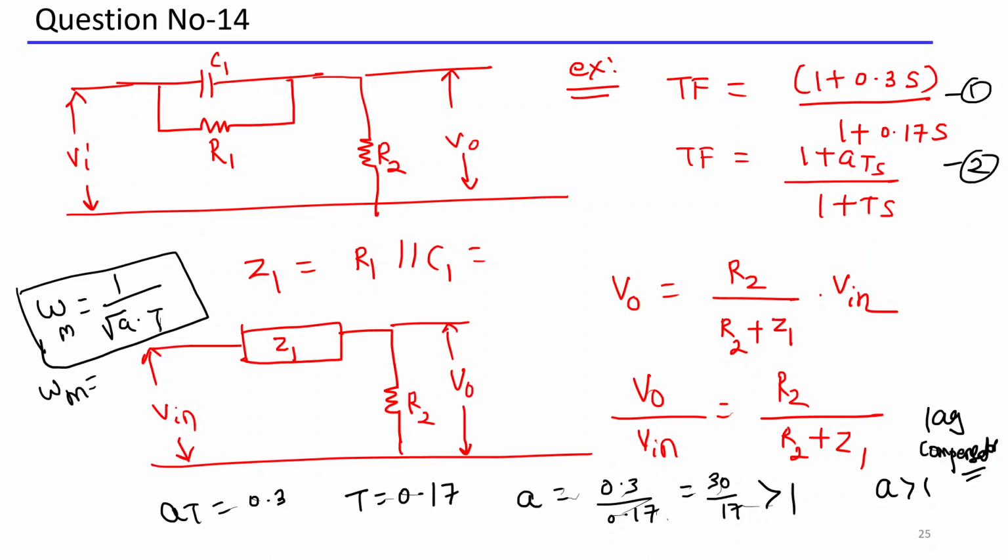Yeah, sure. Sir, the steady state error to the unit ramp input without proportional derivative filter is ess equal to 2 zeta by omega n. And this is without the proportional plus derivative filter. And it is asked to find the value of k when the steady state error for tracking ramp input may be eliminated. Okay, you are giving a ramp input. Yes, unit ramp.